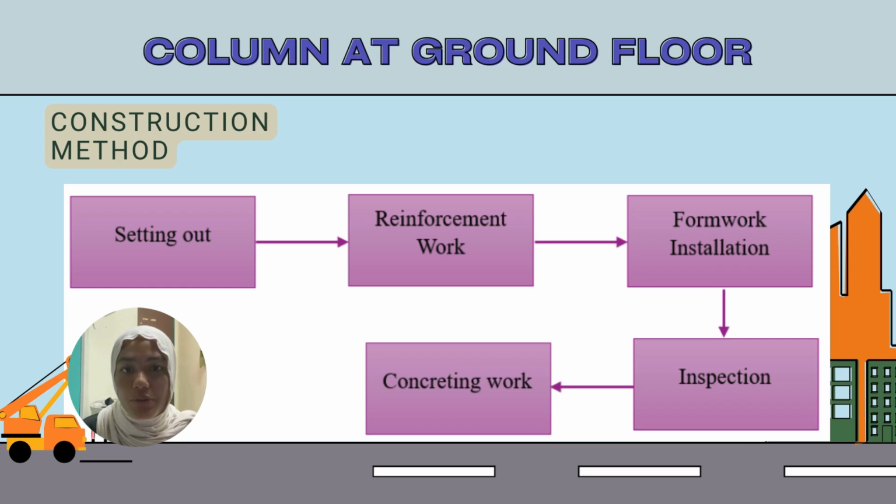So before we do the concrete, we need to do the inspection first. This inspection ensures that all preparatory works are complete and meet the design requirements. We need to inspect the size, spacing, vertical alignment, dimension, bracing, and check the cover block also.